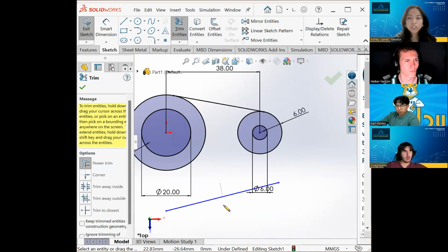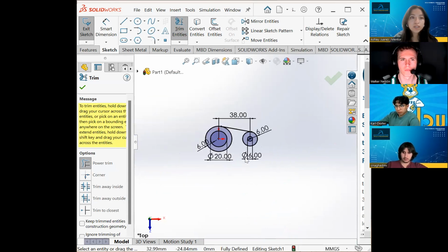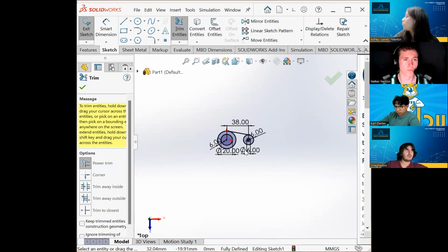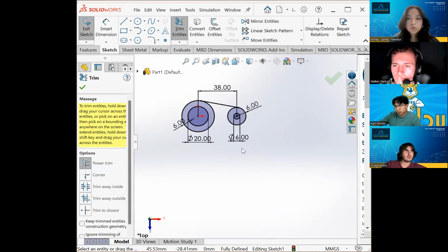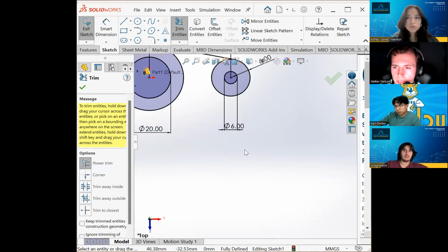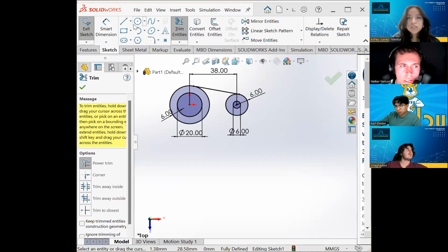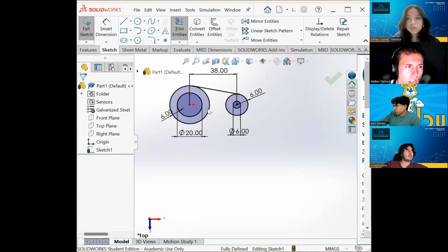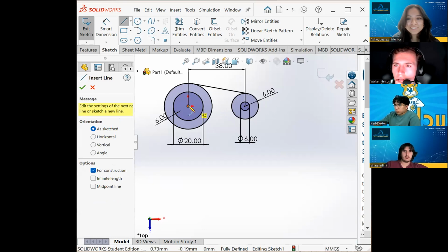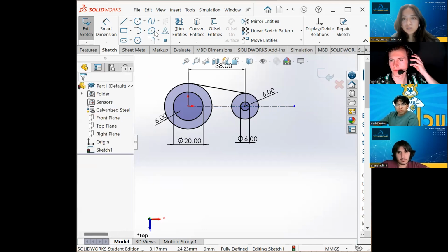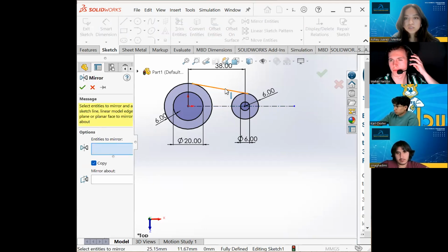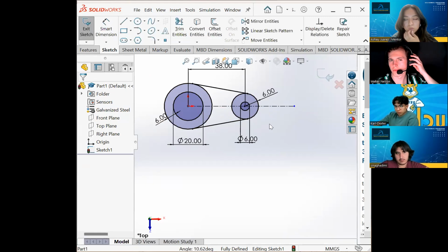That's the thing about tangent relations. That's when order comes into play when we're dimensioning sketches. For everything else, order shouldn't matter, but when we're doing tangent, SolidWorks trips out because circles are always unpredictable. So I'm actually going to follow Adrian's observation here, and I'm going to use the mirror entity because I don't want to do this again. And it's a lot simpler. Cool. So I'm going to mirror entities. I'm going to mirror that line about this line. Cool. Everyone say thank you, Adrian, because he caught that super quickly.